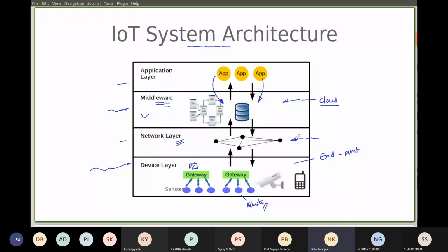Let's say you are interested in modeling latency issues. For example, if you have a temperature sensor and if the temperature crosses a certain limit, then the cloud platform should send a command to turn off the heater. So the latency, the delay, is very important in this. So you want to test if there is delay in the network, will your system work?